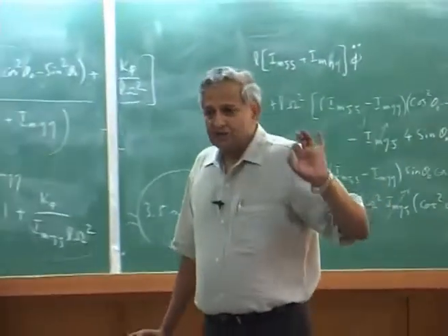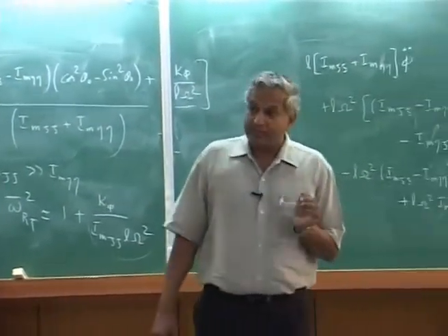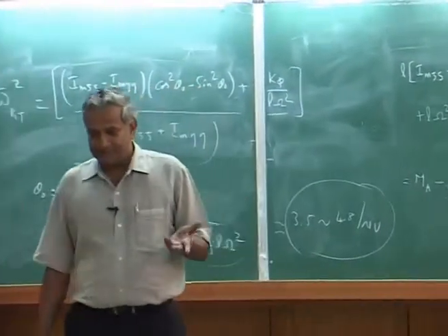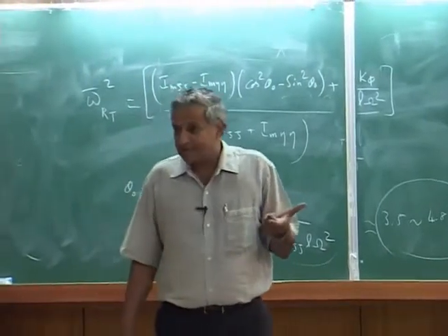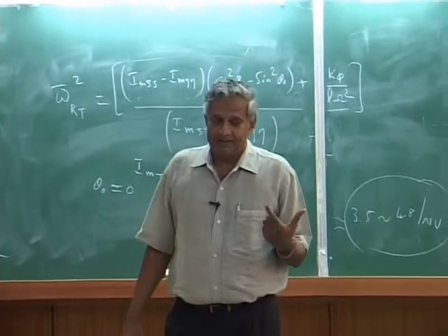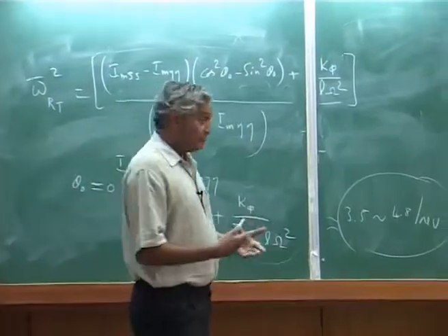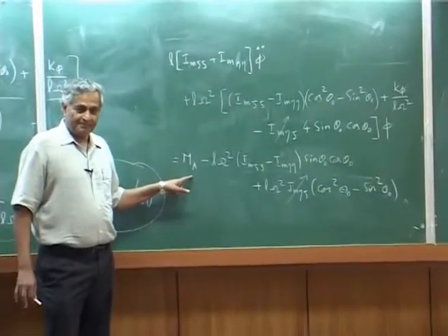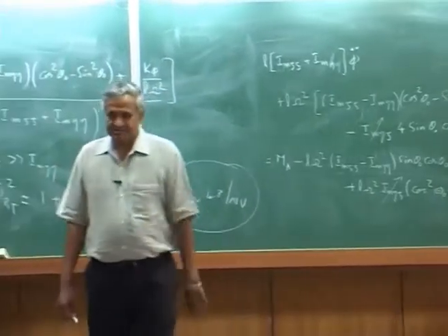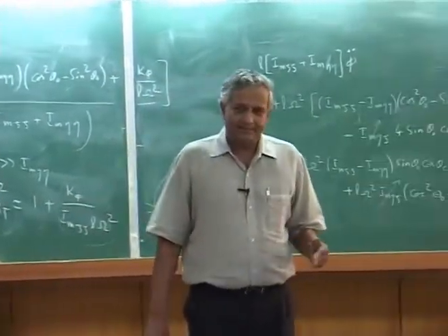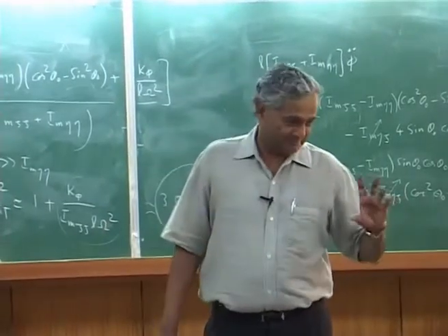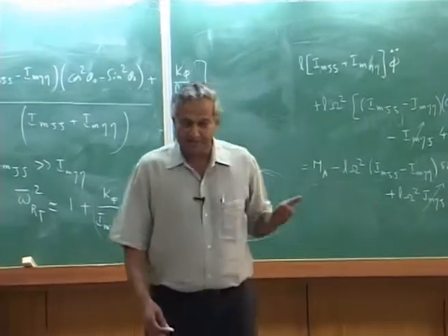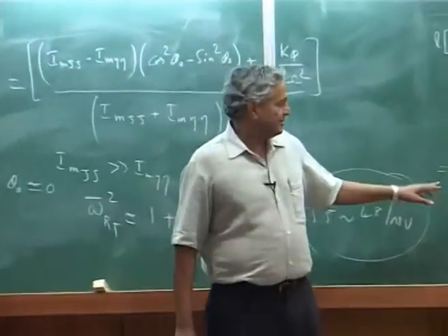Now this is all for an isolated system. But if you ask what about the damping in torsion? Okay, lead lag we discussed. The damping is very small and usually an external damper is provided. In torsion, the main damping comes because of aerodynamics. Usually it is about 10%. That's why there is no damper provided in torsion. Okay. Flap is heavily damped. Lead lag, you put an external damper. Torsion is also damped out.